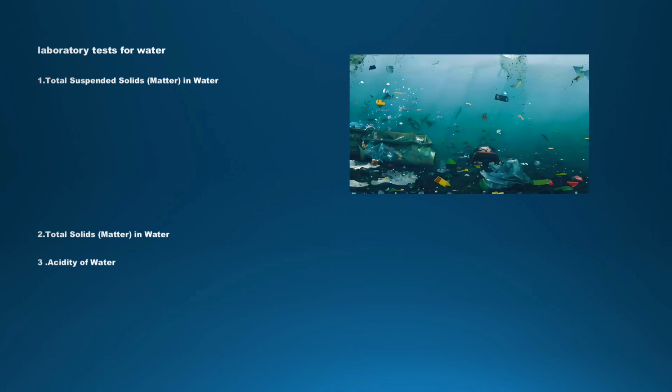Now let us see what are all the laboratory tests for construction water which we need to do. Total suspended solids in matter. What is total suspended solids in matter? Don't worry, it is a very simple term which we all know. It is nothing but the floating impurities in water. The water is having a lot of floating impurities like paper, waste, dry leaves, all those things. That water is not good for using in concrete. We need to remove all these materials and make the water clear before using it in the concrete for mixing or any other curing purpose.